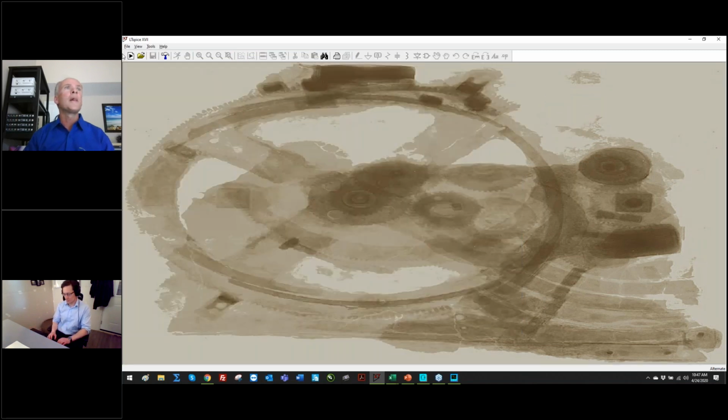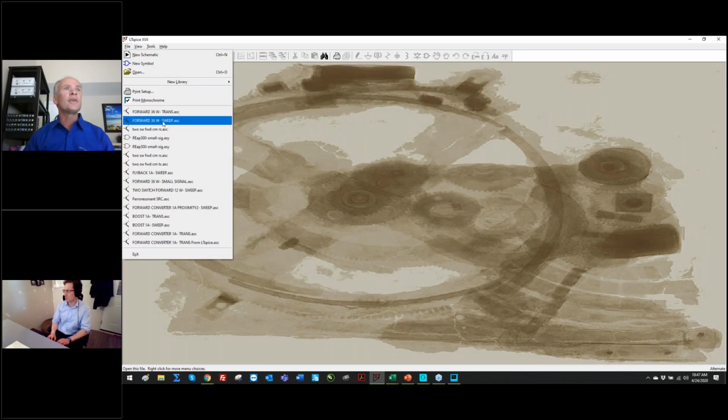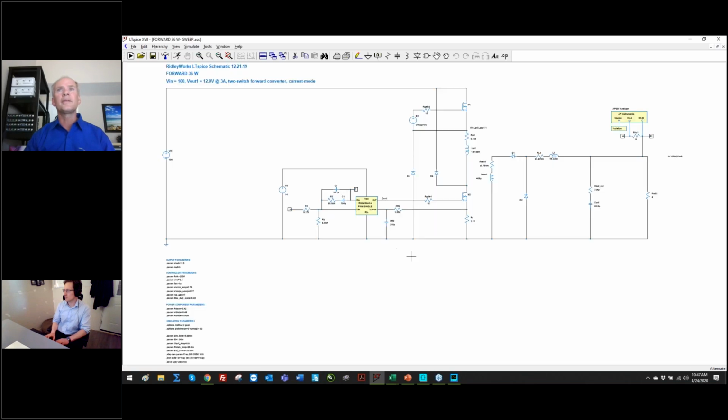Well, instead of using small signal models, we can take a large signal circuit, put a frequency response analyzer on it, and just sweep the large signal circuit. So that's what we're going to do here. Fixed input voltage, fixed load. We put one of our analyzers on. This is the AP300 model that goes in here. Got all the parameters set up for that. And now we're going to sweep through that circuit. So click on the run button.